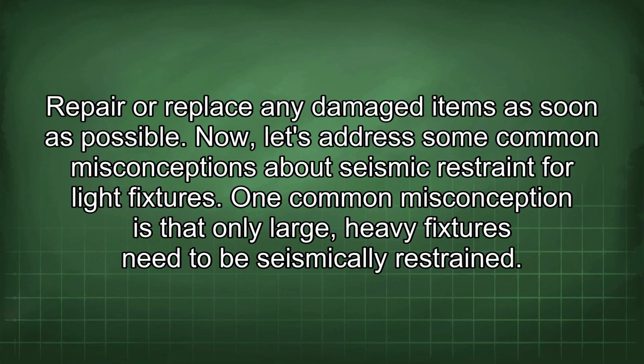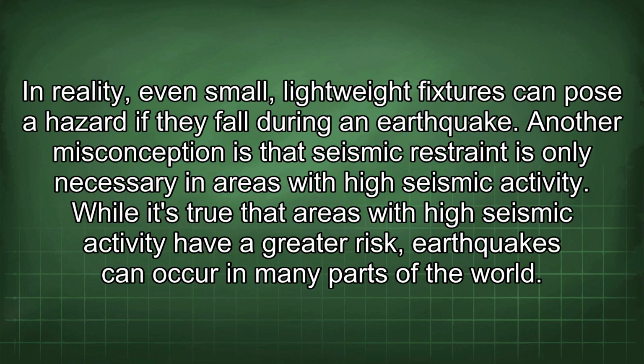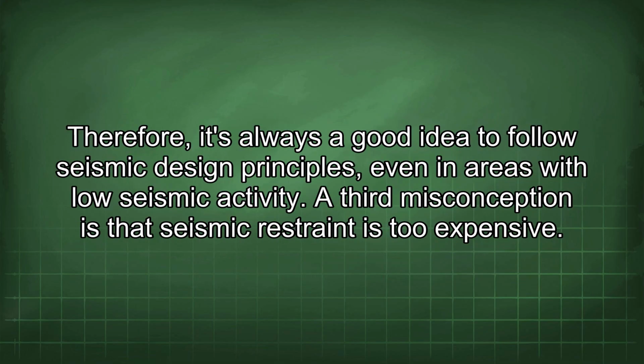Now, let's address some common misconceptions about seismic restraint for light fixtures. One common misconception is that only large, heavy fixtures need to be seismically restrained. In reality, even small, lightweight fixtures can pose a hazard if they fall during an earthquake. Another misconception is that seismic restraint is only necessary in areas with high seismic activity. While it's true that areas with high seismic activity have a greater risk, earthquakes can occur in many parts of the world. Therefore, it's always a good idea to follow seismic design principles, even in areas with low seismic activity.